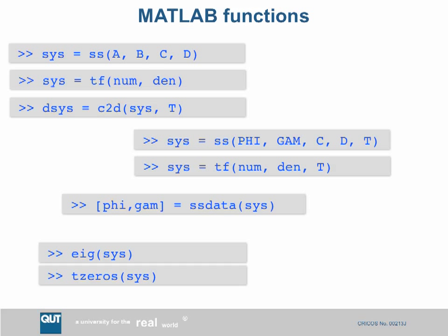Second order system, it's got 2 poles. I have to tell MATLAB where to place 2 poles. So p is a vector that contains 2 poles. Now, they could be 2 real numbers. It could be minus a half and minus a half. That's a silly number. For the z-plane, it'd be better to say a half and a half. Yeah? If they were complex, then they have to be given as a conjugate pair.